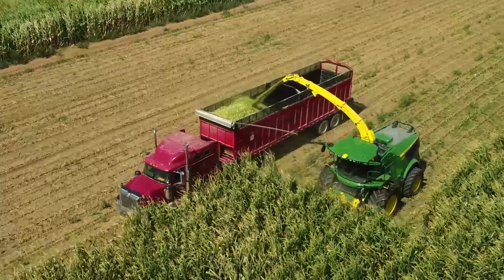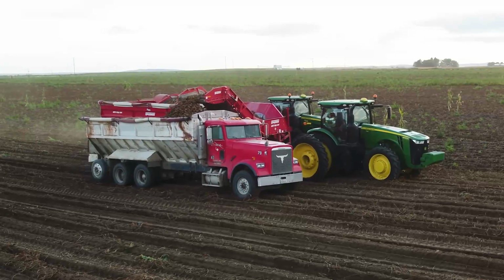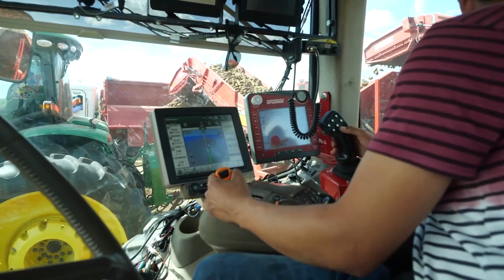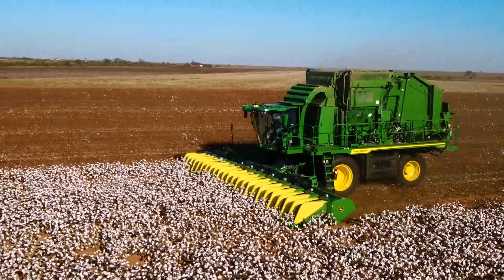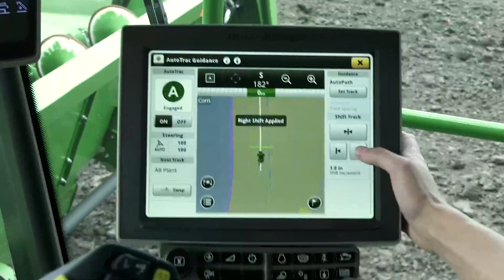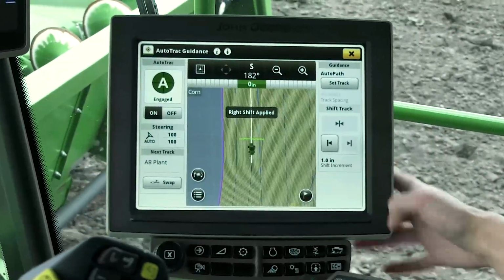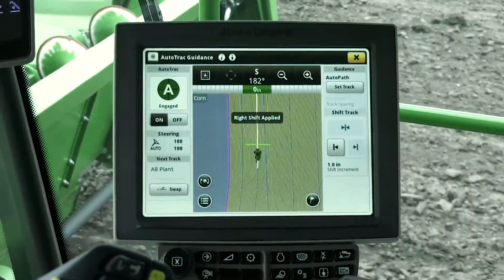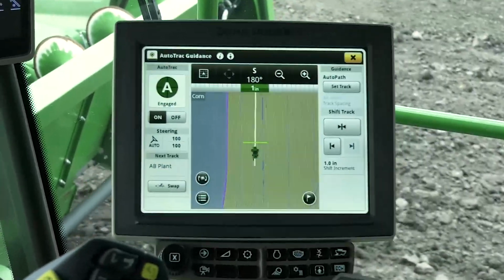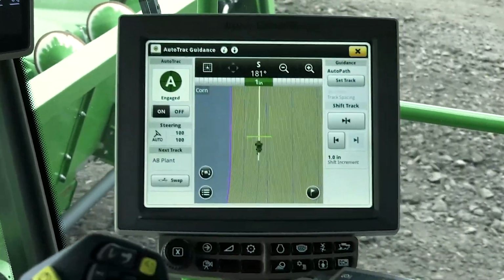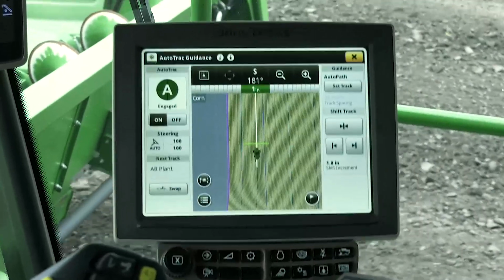Users with 22-1 Gen 4 software released in June 2022 will have the ability to shift up to 12 inches, increased from 6 inches in the 21-3 and older Gen 4 software. If the 12 inches of shift have been used up, and the direction of travel and heading angle changes, the shift will become available again to allow continued correction around curves or in headlands.